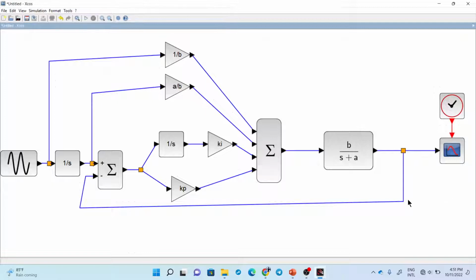Okay, so I explain again the concept. First, you have dynamic system. You have input VA, and output is supposed to be omega. You need this omega to feedback, so you need this sum. Okay, so 1 plus 1 minus, and here is omega d. So forget this for the moment. Just know that the input to the sum here is omega d, and then the output of this comparison is error.